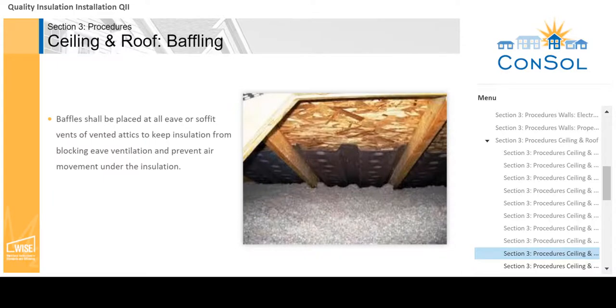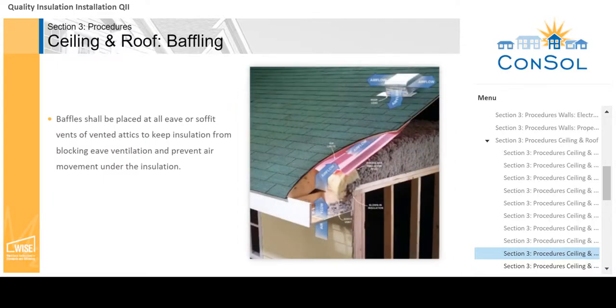Baffles shall be placed at all eave or soffit vents of vented attics to keep insulation from blocking eave ventilation and prevent air movement under the insulation. The required net-free ventilation area shall be maintained.